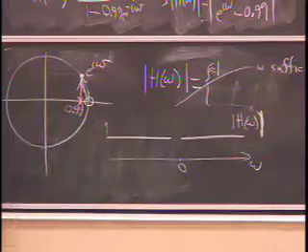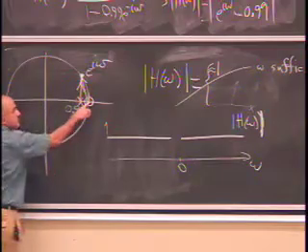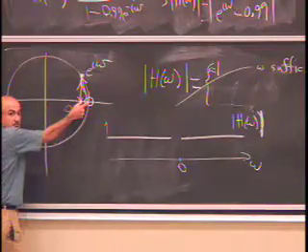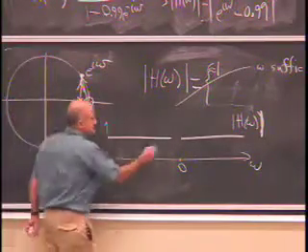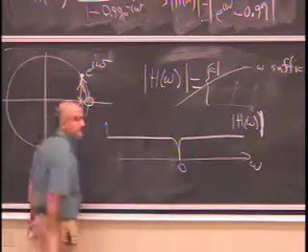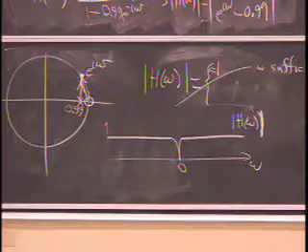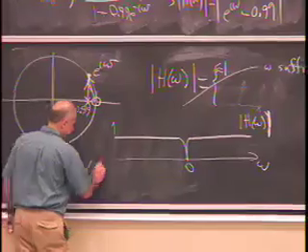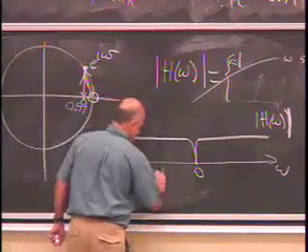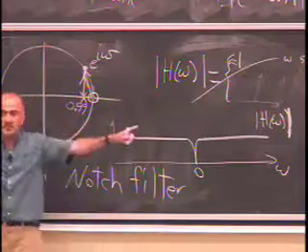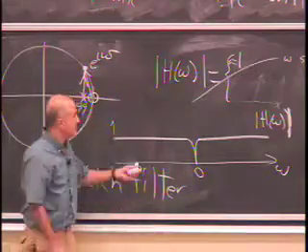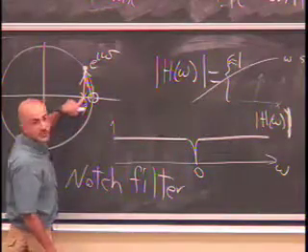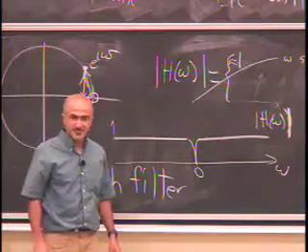What happens at 0? Omega goes to 0. The denominator is finite, small but finite. And the numerator is what? This is a very neat filter. It's called a notch filter. It passes everything, but yanks out DC and frequencies very close to DC. If you want this to be sharper, you make the 0.99 even closer to the unit circle.